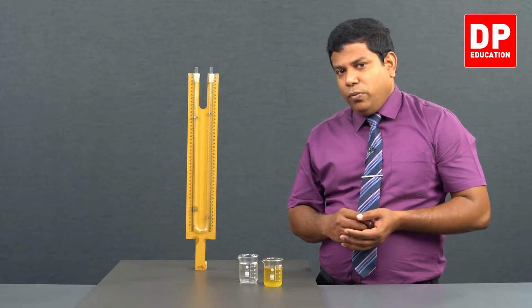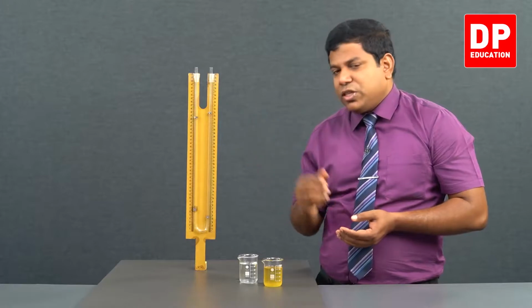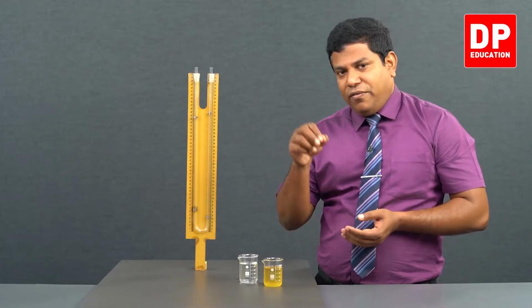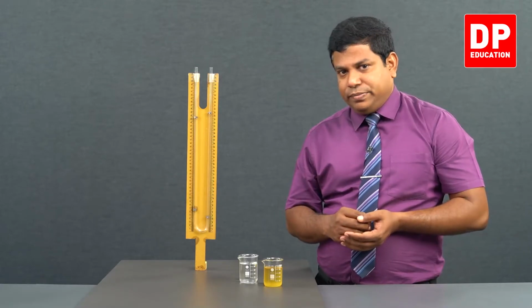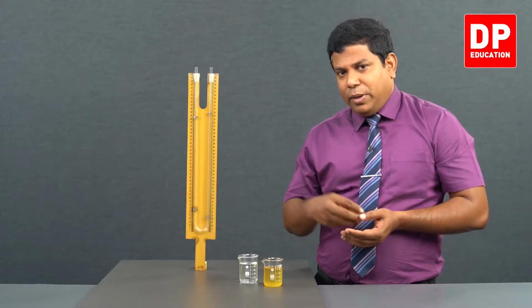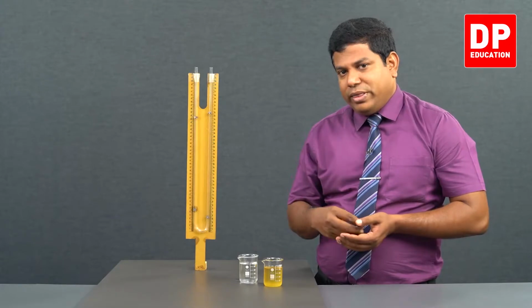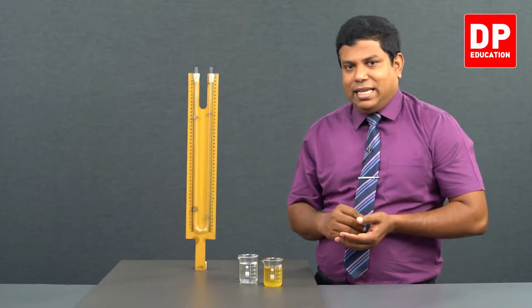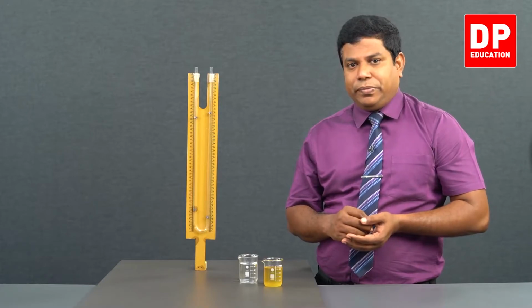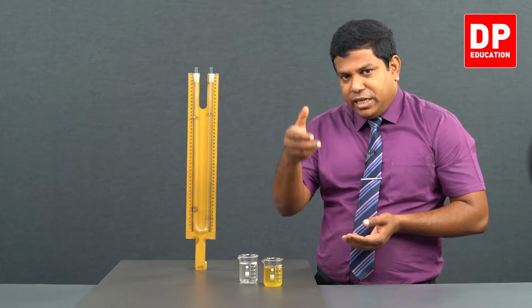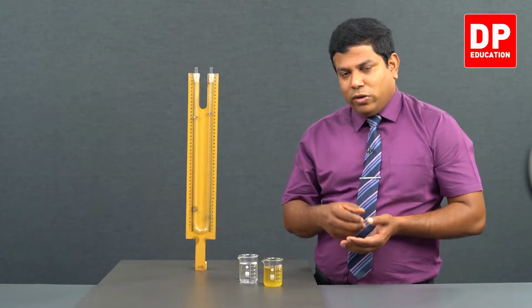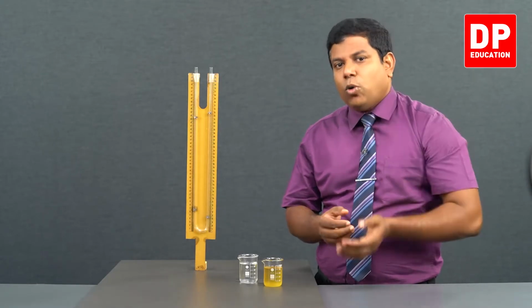Then what I will do, on one arm of this U-tube, I will fill the coconut oil in it. So, what will happen, in that arm, coconut oil will fill for a particular height. Let us say it fills for 10 centimeter. So, because of the pressure that coconut oil exerts, on the other side the water level will have to go up.